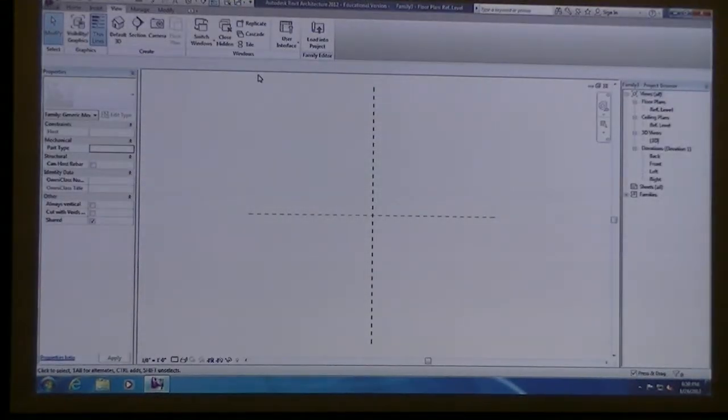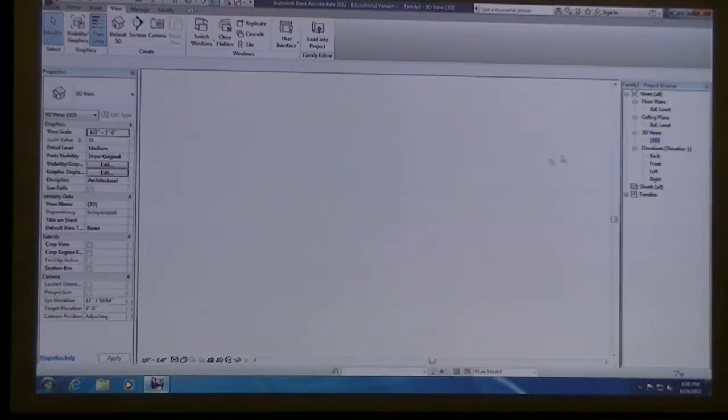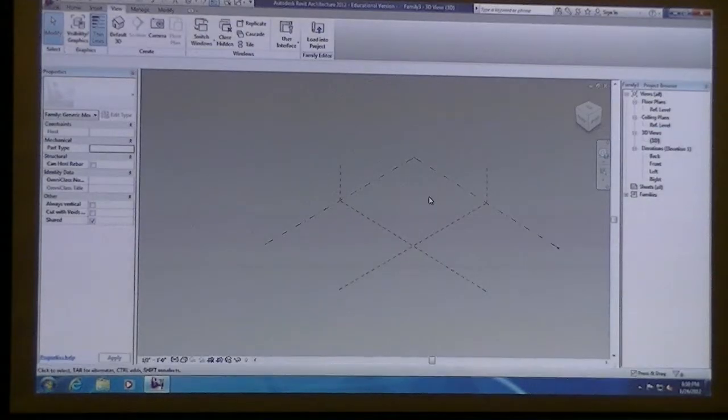They moved it. So the adaptive component is basically a set of points that we can create. It'll just be reference points. If we draw a set of lines to connect to those reference points, when we bring that component into another file, when we place those points associated to, let's say, a wireframe rail, like we're about to, it will always snap those points to the geometry that you've already created.